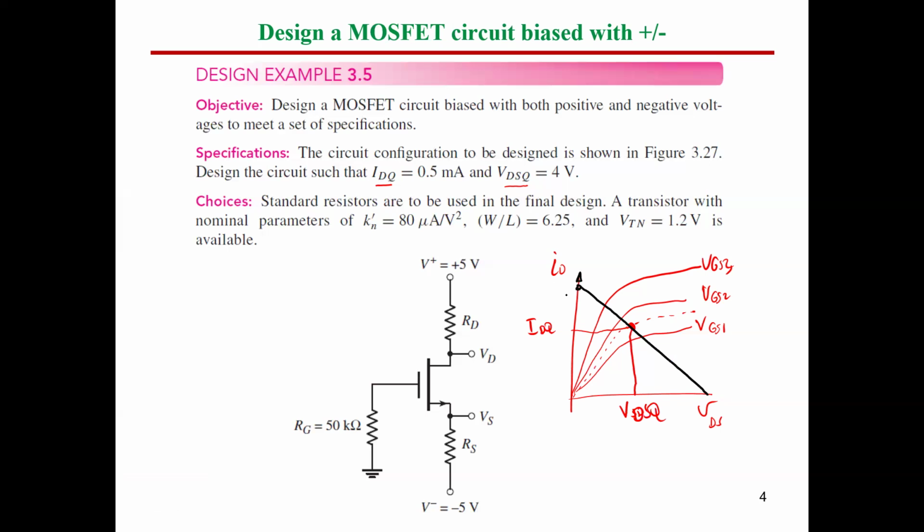We will see what is the equivalent equation of this value. And also this is another certain value for V drain to source, what the equivalent value of this VDS in terms of other parameters. You will see that in the design. And this is our Q point. So the idea is design in order to achieve a certain operating point on the ID VDS characteristic.